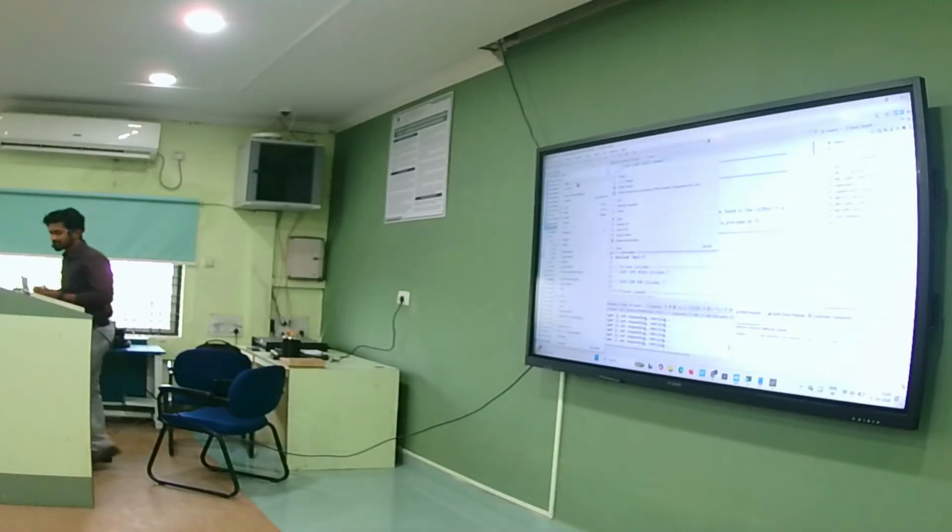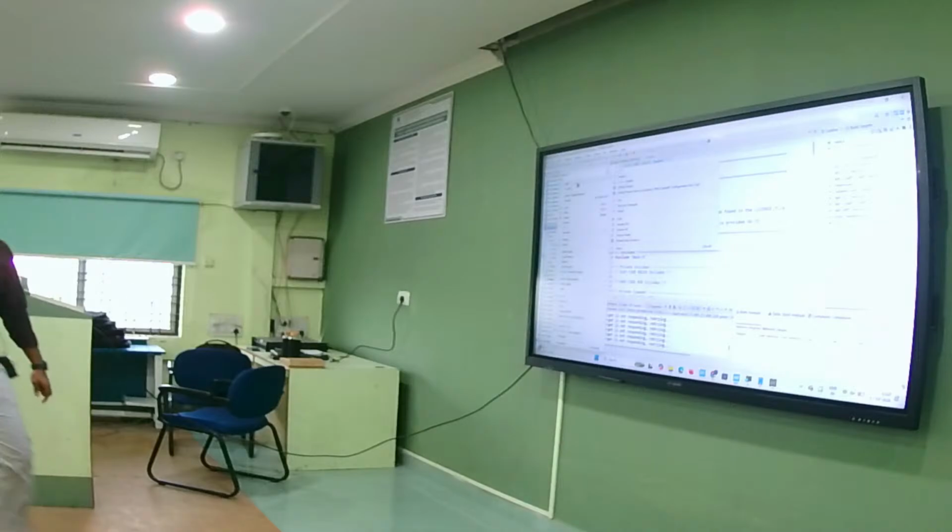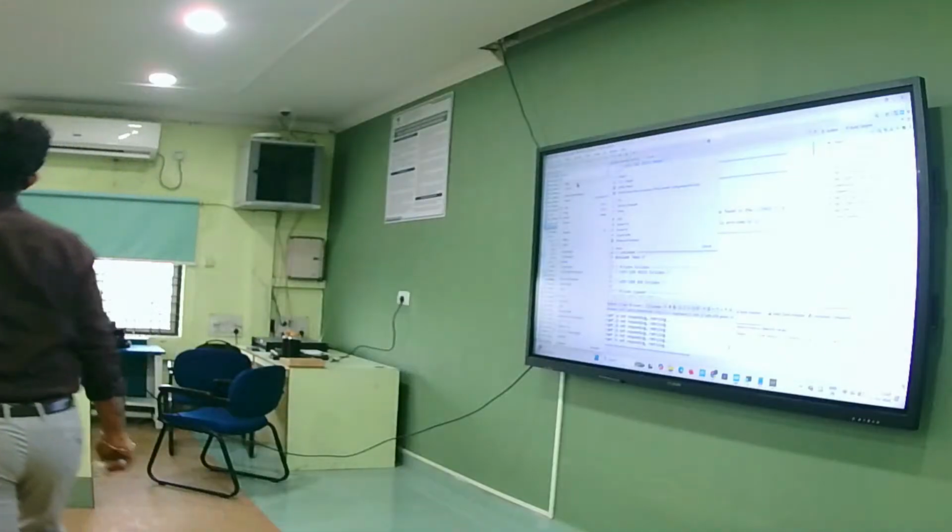See what we are going to do. I'll just tell you. We are creating one folder, the NEAI folder. Inside we will create two more subfolders, INC and LIB. Why INC and LIB? Because these two we want to add: the .h file and libneai.a. So these two files we are going to add here by creating a folder and subfolders like this.